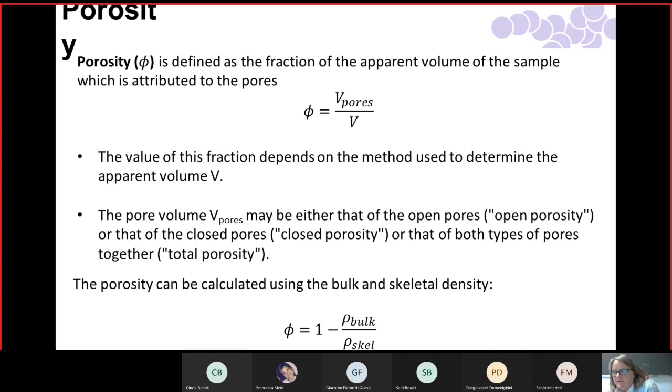That would give you one of 97%. So depending on your conditions, people report 90 to 99%, depending on how that aerogel was made, what is the resulting bulk density and skeletal density. So that is a simple way to estimate porosity, but it is, again, an average way of doing that.